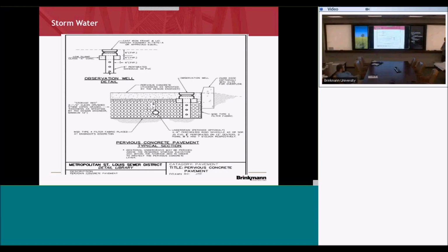But you really got to look at that and see what, like Kendrick said, how it changes. And you got to think about timing. If you put it in too early, you could silt that basin up during construction. You have to replace it. So you may want to think about waiting to the end to hog it out and haul it off. But you also may be short of material on the site or long of material, and you might need that dirt.